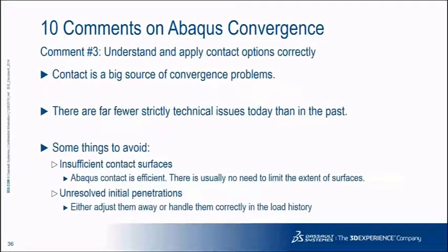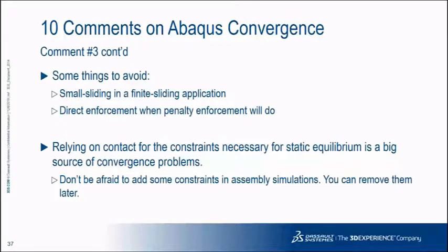Understand and apply contact options correctly. Contact is a big source of issues. These are not really technical these days like they were in the past, but sort of self-inflicted by defining insufficient contact surfaces, or having unresolved initial penetrations, or using small sliding and finite sliding applications, or using direct enforcement when